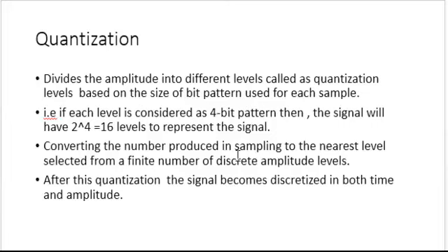So after quantization, you have the signal input. The continuous signal will become discretized in both time and amplitude. For example, if I am going to use a 16-bit pattern for representing the amplitude, then I can represent the amplitude with nearly 2 power 16 levels. So that is about the quantization. Now we'll see an example based on this.